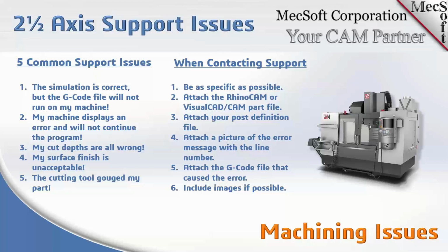We mentioned in the earlier slide about your work 0. If you haven't zeroed the machine at the exact location that you've selected in the program in RhinoCam or Visual CAM, obviously your cut depths are going to be all wrong, and you're going to be scratching your head, wondering and wasting cut material on the machine because those are not coming out right.